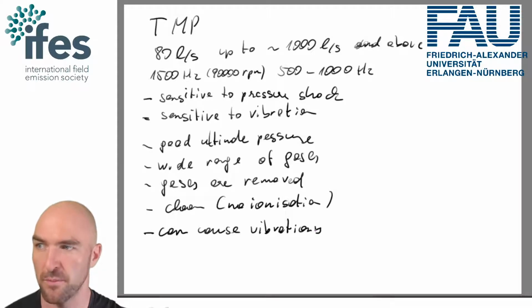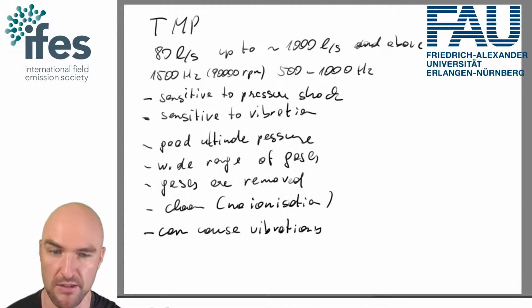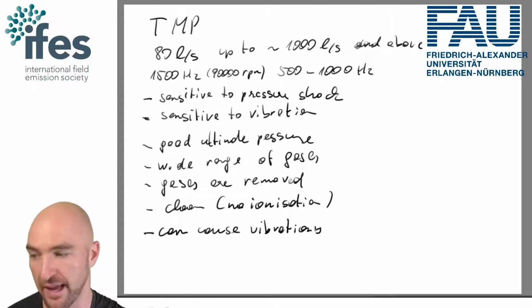But modern magnetically levitated turbo pumps or hybrid bearing turbo pumps have very, very small amounts of residual vibrations. And for electron microscopy, you can even get special turbo pumps with extra low levels of vibration.